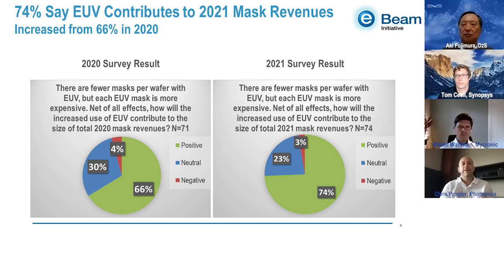The thing that makes EUV special is it's one of the mask technologies where materials costs now drive a disproportionately large amount of the manufacturing costs. Blanks, pods, pellicles, everything, could well go up over 50, 60% of the build cost of an EUV mask. So when complexity drives negative yield on the mask side, that has a very, very large impact on manufacturing cost. So the prices will need to go up dramatically to compensate for that.